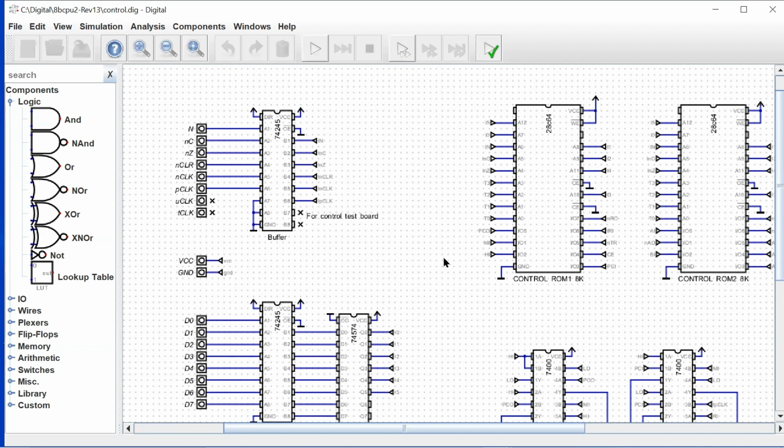So we'll pretty much be able to control all of the data flow in the computer if we need to. And my hope is that won't be required, because we're going to test each board individually, and that means the only thing left that's a little bit questionable will be the backplane board. But we'll have to use slightly different testing techniques for the backplane board. That's really going to be just point-to-point connection testing, because that's pretty much all the backplane provides, all the buses.